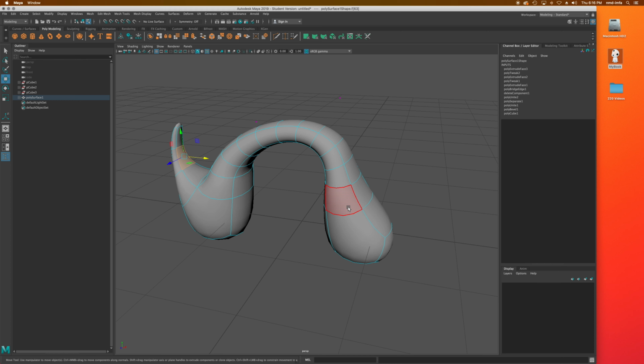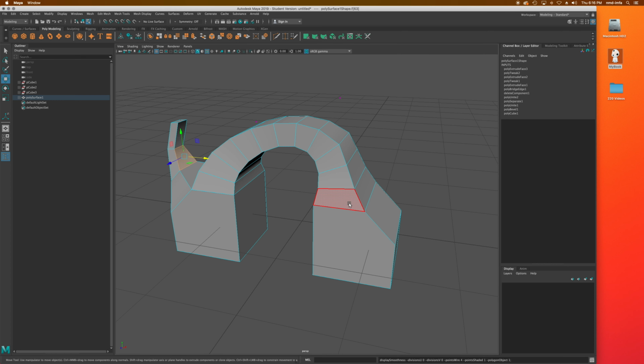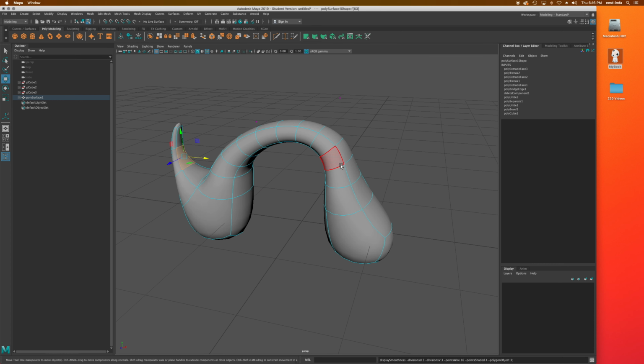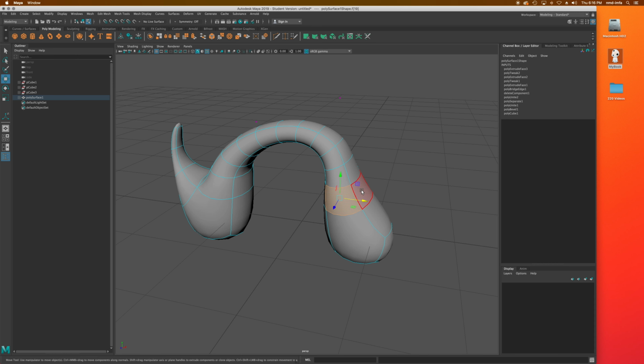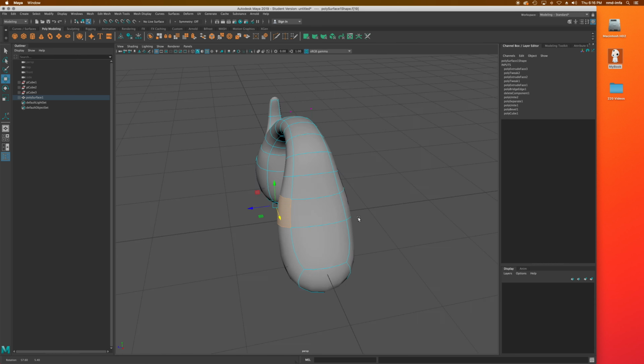Because, you know, if I took this object and smoothed it, it's going to subdivide all these polygons into double or triple the number that are there, and then it's way harder to control. But by having this preview mode, I still have the low number of control polygons, but I get to see what it looks like when it's smooth. You're going to see how powerful that is, and I can't state enough how important it is to switch between that 1 and 3 mode.